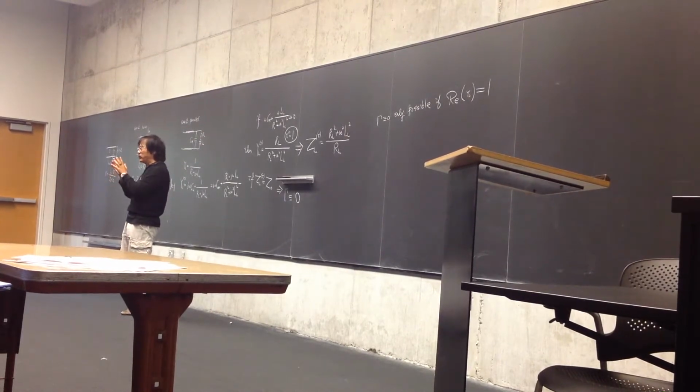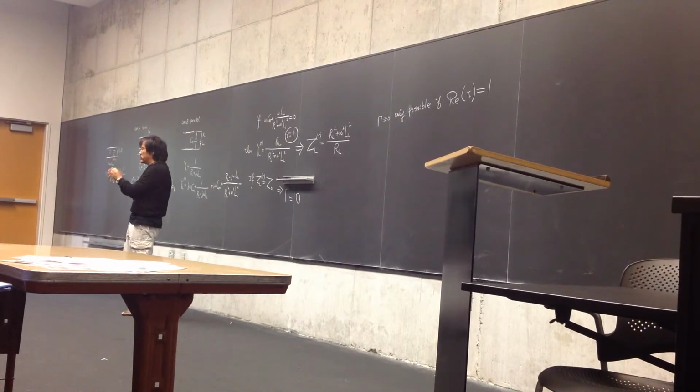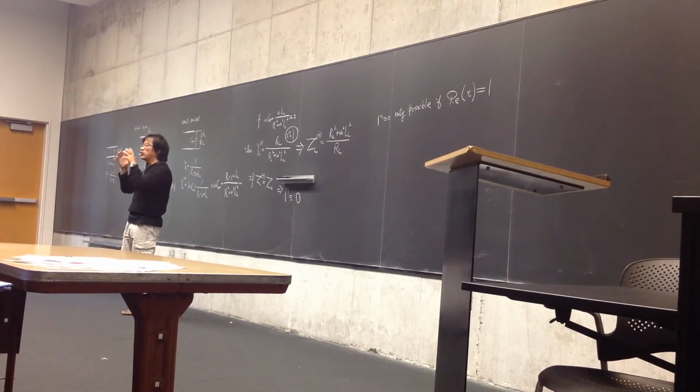And that's the reason when we talk about matching, we use the Smith chart as an admittance chart. So here, another thing to tell you is how you use the Smith chart as an admittance chart. You first use it as an impedance chart and rotate 180 degrees, then you are able to find the admittance. That's a trick to do that.